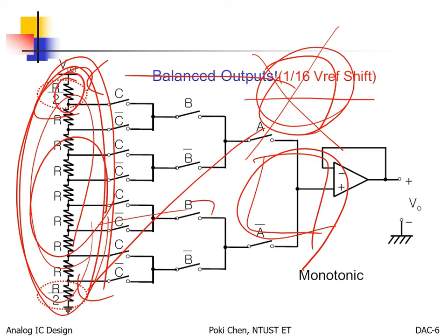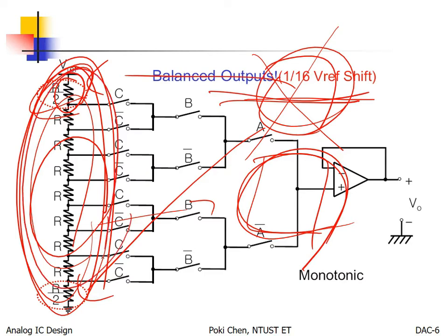So what you can do? Don't divide it. And what else you can do? Anybody? How to achieve R/2 by the same unit resistor? Piece of cake. Two in parallel, right? That's it. Don't cut it into halves, that is some kind of silly implementation. All those to be matched should be exactly the same.